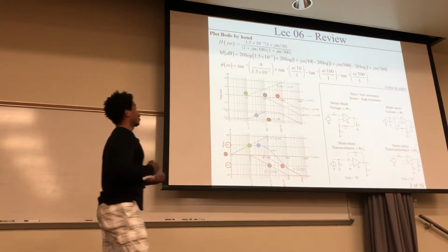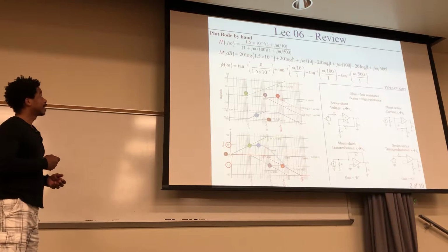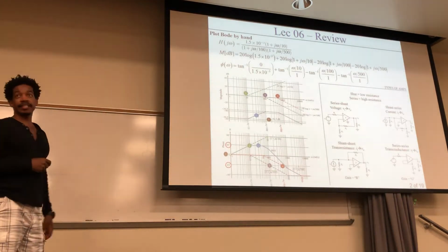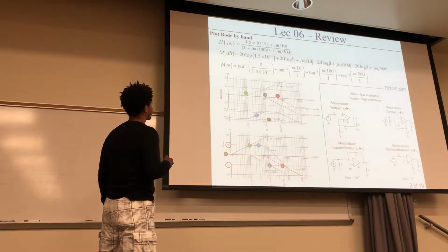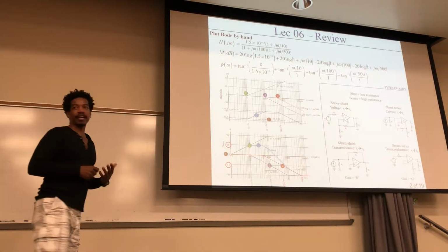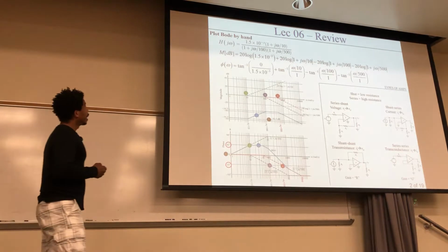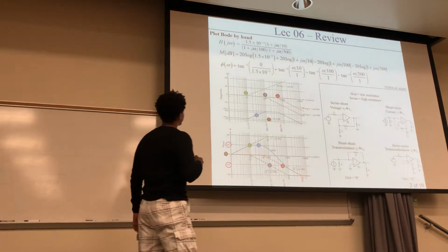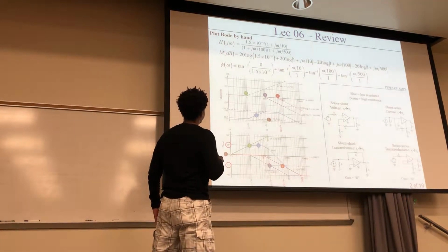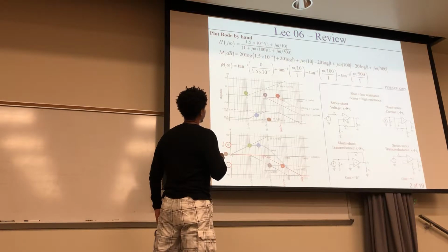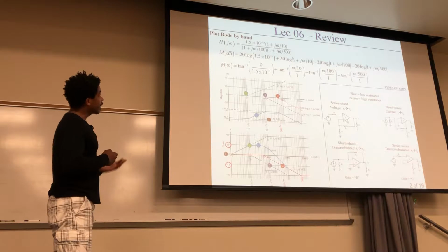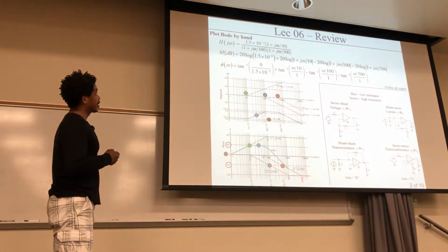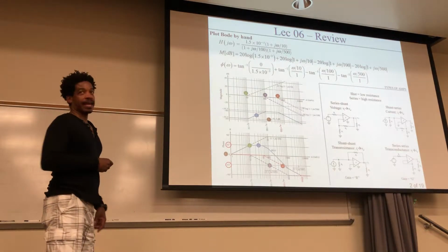what typically happens is that you're given a transfer function, and it's steady state. So that's why this is just j omega and not s. S is typically for transient analysis. But with steady state, then it's just j omega, and it may not be in this form, right? But what you need to do is, if you get it into this form right here, then it makes it a little easier to work it out by hand.